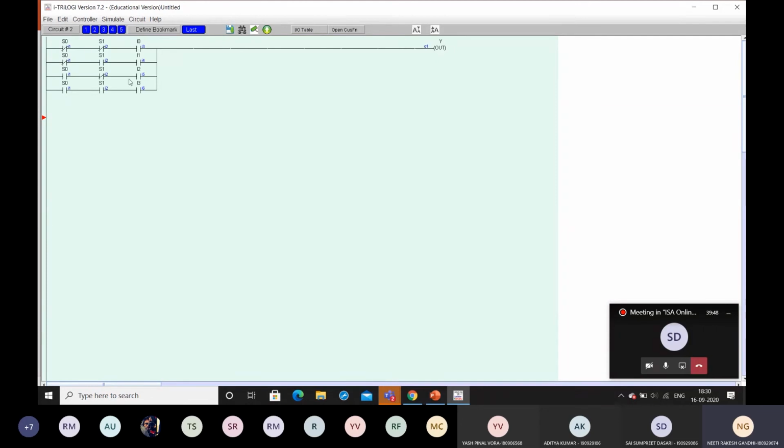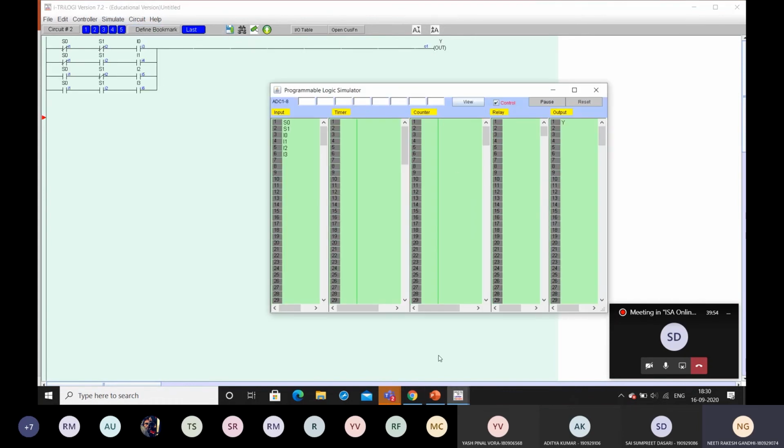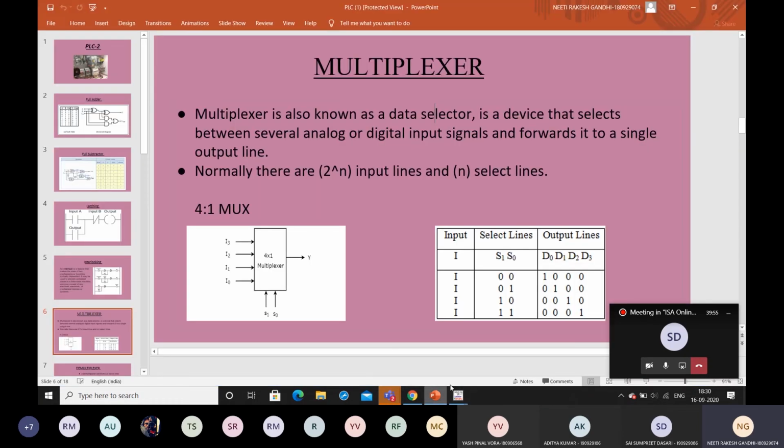As I said before, a mux is a many to one function. We have only one output, we didn't use four different outputs. So now I'm going to try to simulate this and let's try to implement all four. Now when I'm giving it 0 0 and my first input is high, I should get an output.